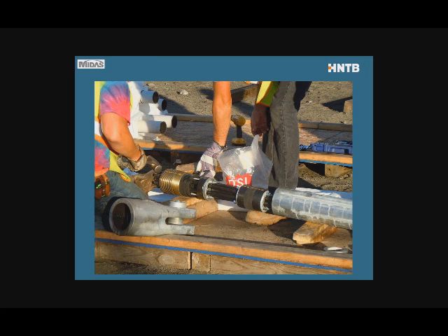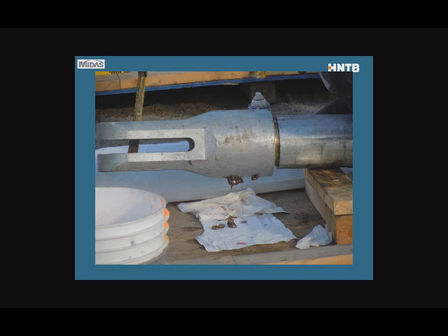So they can squeeze the whole. These are neoprene collars, and they squeeze the neoprene collars together, and that expands the system, that ensures water tightness and proper seating. In the foreground, you can see a machined, or actually a cast, pin piece, and that will be threaded on the thread of the anchor plate.